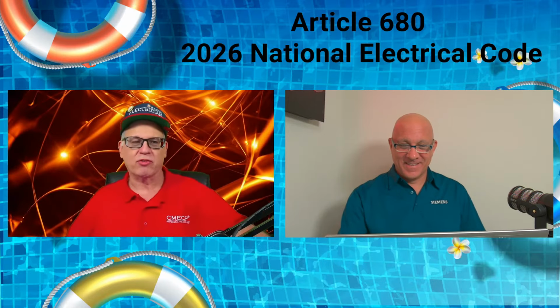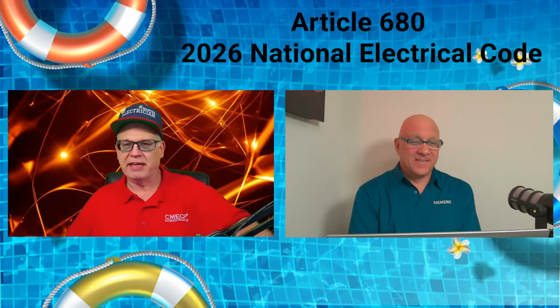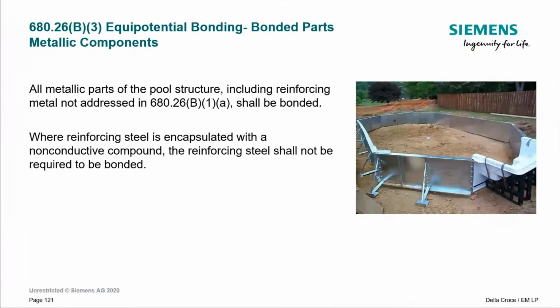All right. So the next one that we're dealing with here is 680.26(B)(3). And this is again still talking about equipotential, but we're getting to another part of the equipotential bonding grid. And this is bonding of parts to metallic components. All right, look at this pool. So this pool right here, now this might get a vinyl liner. Absolutely. This is not going to be a conductive pool shell, but it does have the metal parts, obviously within 5 feet going all around it, right? So obviously it is a conductive shell. It just doesn't fit into the language of the shell.